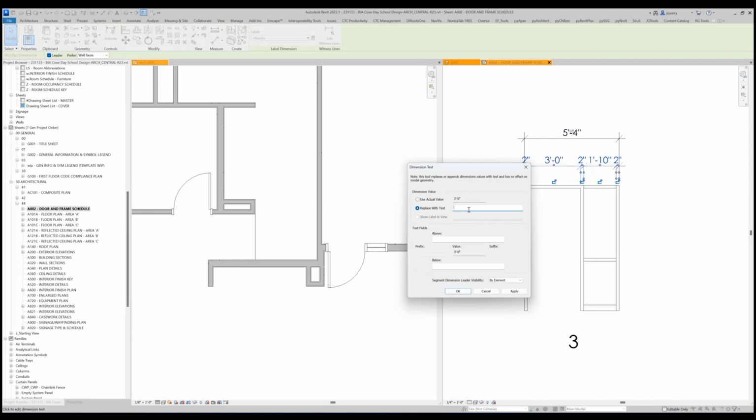What's the difference between the 4 and the 7? The side light width is wider, and it looks shorter. They didn't do a good job of putting the overall on that. Well, it says on 4 it's 4'4", and on the 7 it's 4'7", and 1'11", and then this is the same. Oh my gosh, what did they do? No, it's different. They measured the centered mullions on one and center line on the other. Not consistent. Oh, that's terrible.